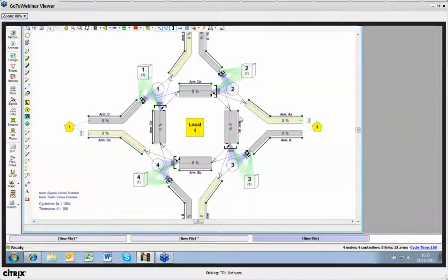The platoon dispersion model takes into account the fact that as traffic progresses from one stop line to the next, some traffic pulls away faster, and some traffic might pull away slower, some turns off, some joins in. So the shape of the platoon further downstream at the second stop line is distinctly different from how it left the first stop line. Now getting that platoon shape at the downstream stop line accurate is the key to getting the offsets between 2 stop lines and 2 junctions correct. So that's why we've got those 2 models.